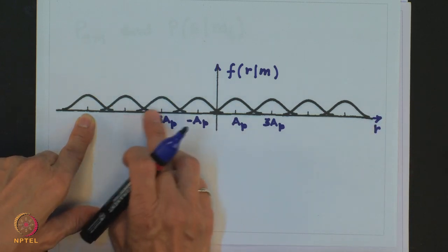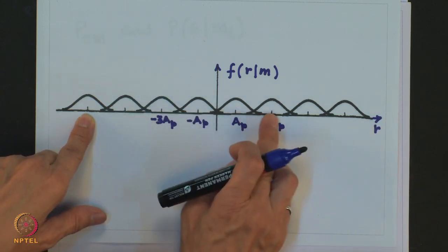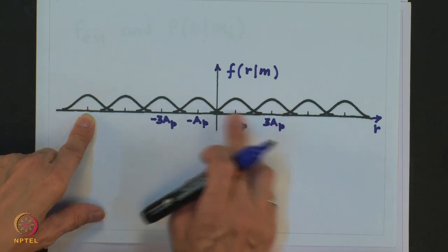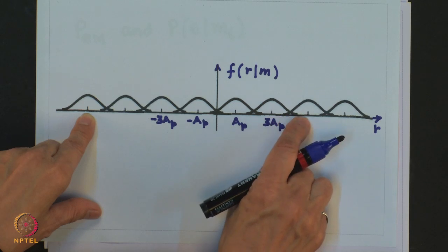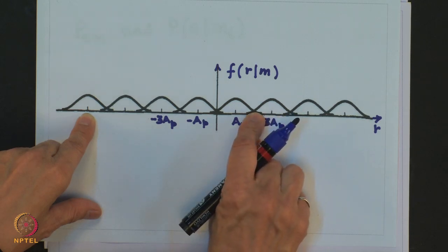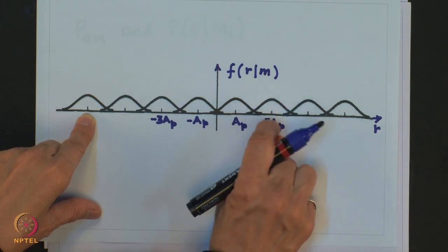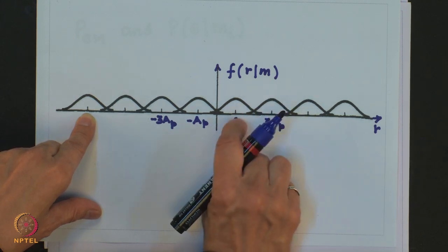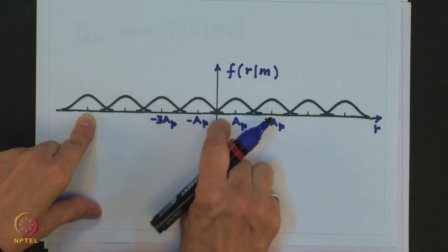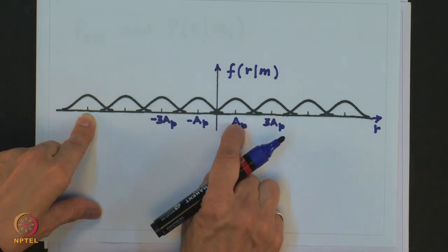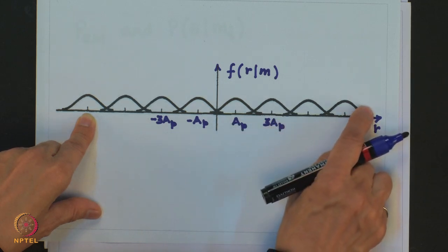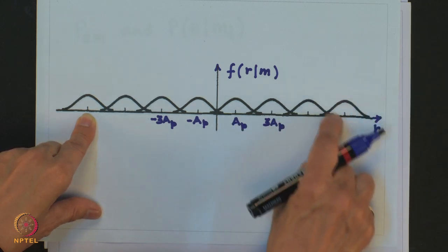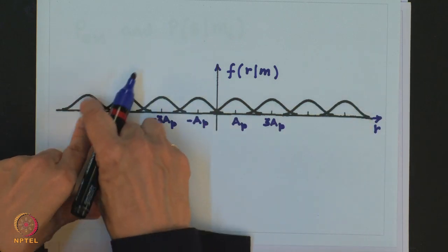As for the remaining symbols, they must guard against neighbors on both sides. For example, if you take this, it has to guard against this neighbor also, and it has to guard against this neighbor also. So, in this case, the conditional probability of error given that we have transmitted any of these signals would be twice what we obtain for the extreme signals in here.